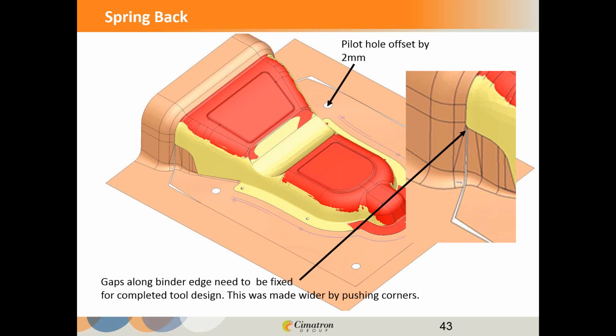You can see that just that slight adjustment in moving the pilot did affect the outcome of the calculation. It affects the total deformation Springback, which tells me maybe when I do offset a pilot, perhaps I'm going to pick one that's further away from the part that has less of an effect, or just put it in an offset location where I know it's not going to cause a problem to the deformation. Something to think about, as we look at the detail level that we're getting into working with this. So we pushed that corner back a little bit further. We stayed 80 thousandths steel safe, or 80% steel safe.